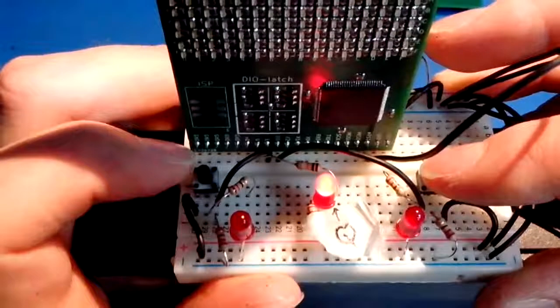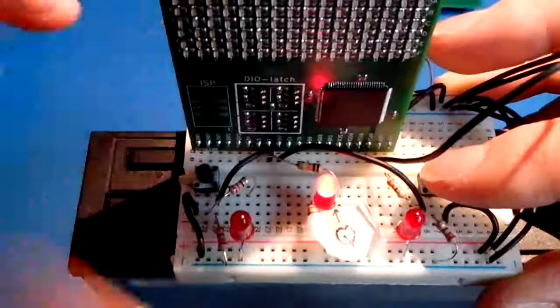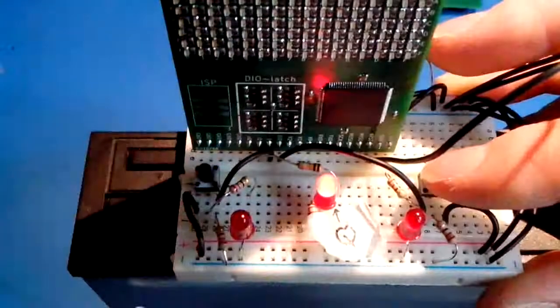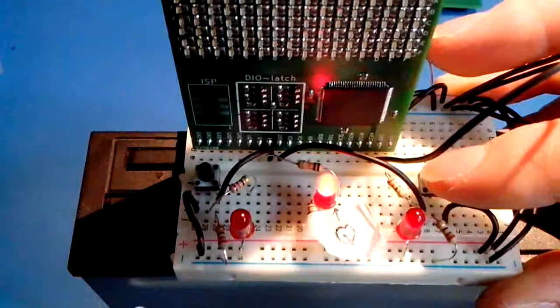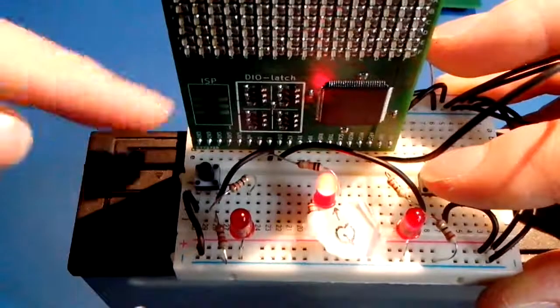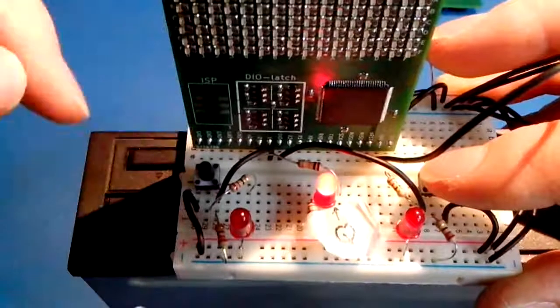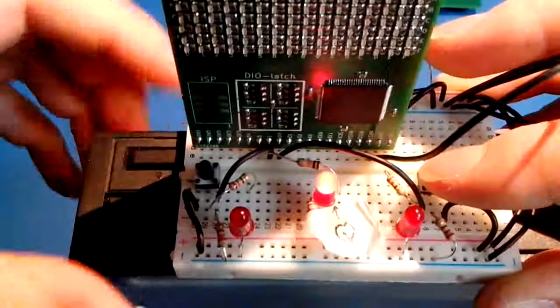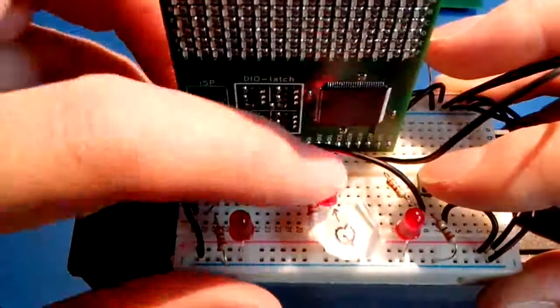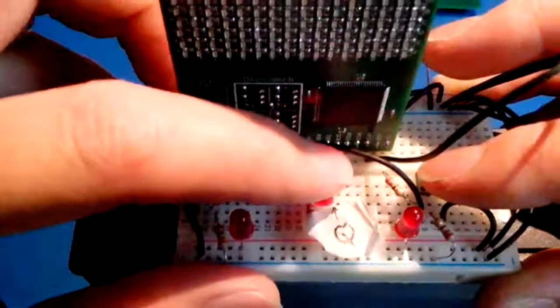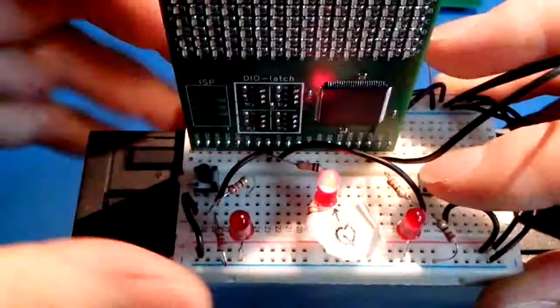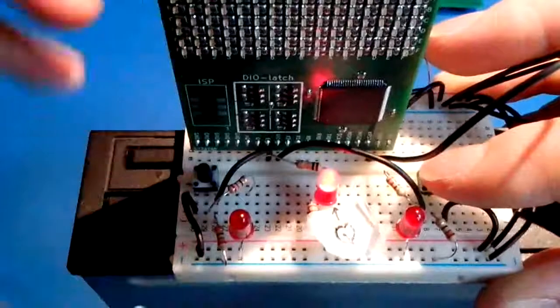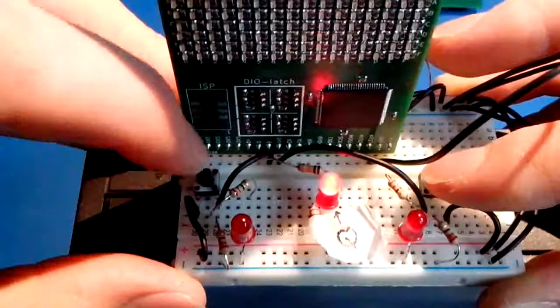One other thing, the whole business with the resistor, and driving the node connected to the RAM's IO, the RAM's data pin, either strongly by the driver inside the RAM itself or weakly by the resistor between the latch inverted output and the latch data input, is not shown here. So I'm simply going to show the Q output and that's it. What we showed on the whiteboard, please believe that, because I'm not going to show it.